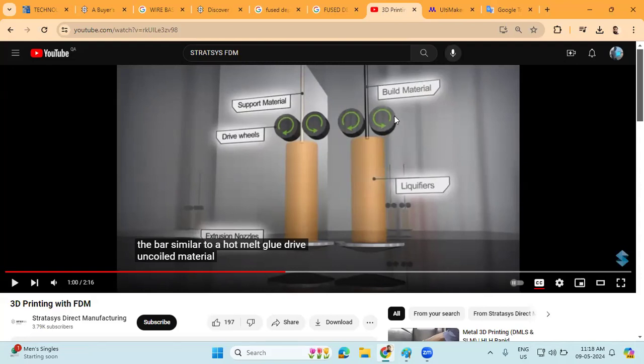The rollers are made of hypalon or polyurethane, and one or both of them have a grooved or toothed surface to create sufficient friction to grab the filament and feed it into the liquefier without slippage. The pressure on the filament between the rollers is typically enough to slightly deform the filament, leaving small tooth marks so as to avoid crushing the filament. This is important. If the filament is crushed between these two rollers, it can cause inconsistent extrusion, which can result in a poor quality print.